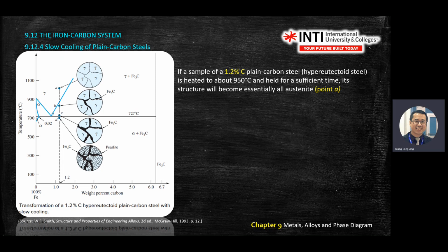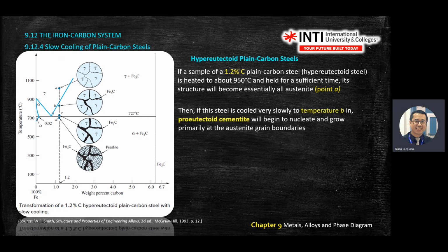What I need to highlight is that for carbon steel, meaning the carbon plus ferrum system, pearlite is very important. You should understand at what temperature, or after you pass through what temperature, you get pearlite. Normally it passes through the eutectoid temperature, in this case 727. For carbon steel, 727, this temperature is important. The rest you read is still the same as the previous few slides.